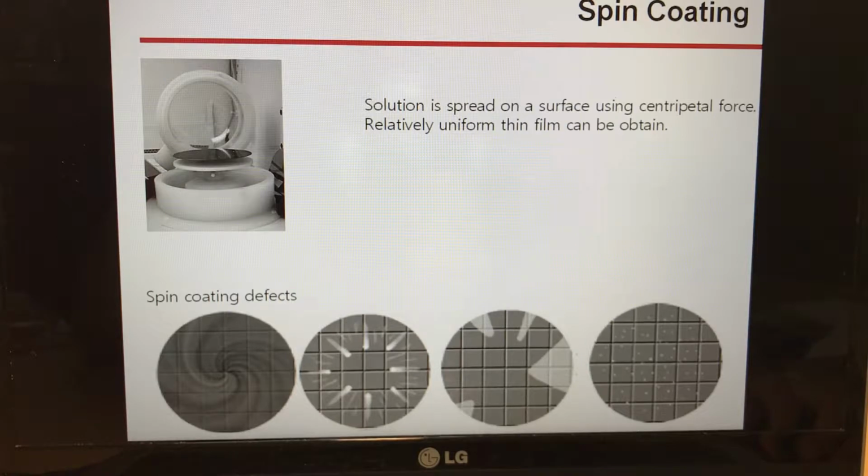When we do coating, we spin the wafer constantly, because if we spin it inconstantly, the wafer's center and edge thickness are different, and this makes device variability and device performance is very low.